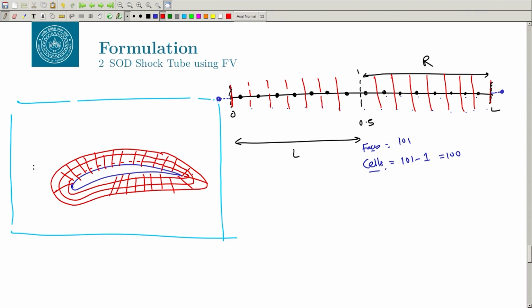In 2D these are very nice quadrilaterals, but you have to match to the outer boundary. So you can have a grid that keeps growing, matching the boundary, any kind of grid. You can have an unstructured grid completely outside. The only thing you need to take care of is that you cannot have overlapping elements. Similarly, here you can do whatever you want and go to your boundary, and you can fill this in the entire domain.